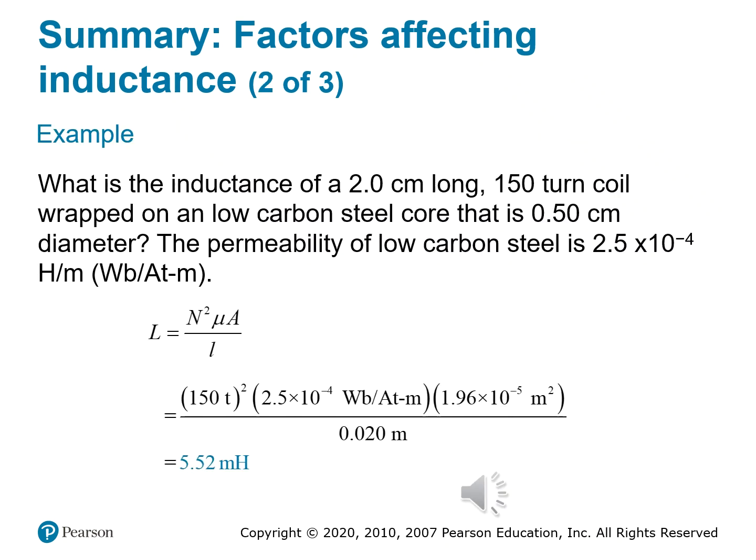All right, on this slide, we're going to look at calculating inductance, the math behind magnetism. So now that we've introduced the formula for inductance, let's walk through a real calculation using actual dimensions and material properties. So the problem here says you're given a coil that's 2 centimeters long, or 0.02 meters. Remember, we have to convert everything to the standard unit, which is meters. If you forget to do that, your calculations are going to be way off by decimal points.